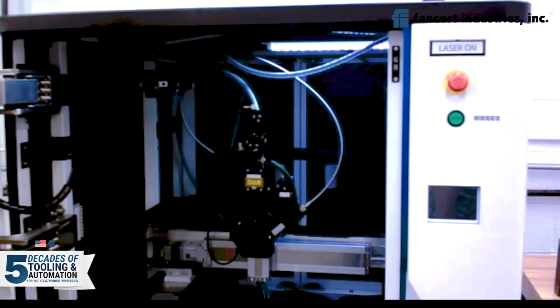We call it the thermal probe. The feature of the thermal probe is that the laser controller gets feedback of the temperature, and you can set an upper and a lower limit of the soldering temperature. Then the laser power is controlled by the temperature feedback in that range to avoid overheating or underheating.